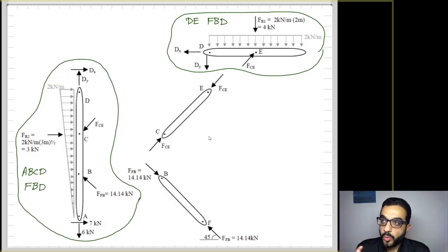So one thing here, I have 4 members in this frame, but I will have only 2 free body diagrams to analyze, because 2-force members are great, but I already used their equilibrium to figure out that the reactions are equal, opposite and collinear. So I cannot leverage their free body diagram equilibrium to solve for unknowns. It's already done. I used this information to simplify their equilibrium.